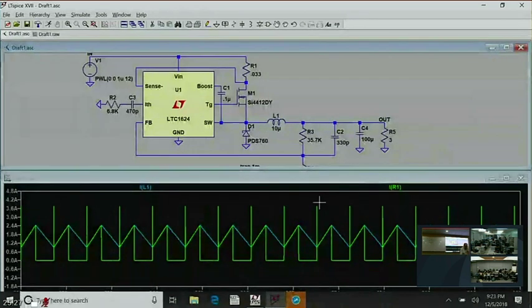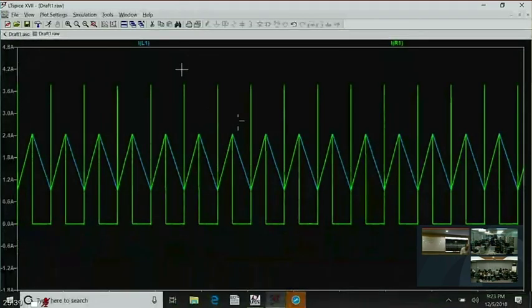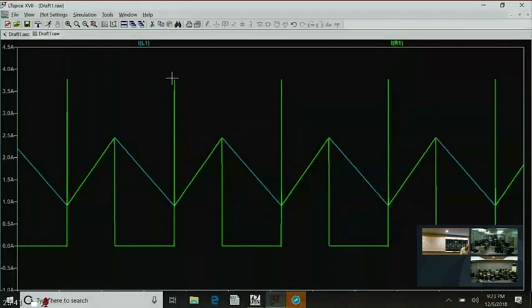In fact, the Schottky diode is the most capacitive thing in this whole circuit. Well, I mean, except for the output filter cap. But other than that, it's the most capacitive thing in the whole circuit. Anyway, so you get all this displacement. You get this many amps of displacement current, and that doesn't go through the inductor.